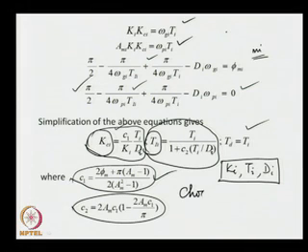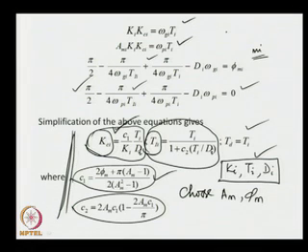So, choose the phase and gain margins for your loops, a m and phi m. Once the phase and gain margins are chosen for the loops, then C1 and C2 constants are obtained. Using C1 and C2 and the knowns Ki, Ti, Di, it is not difficult to estimate the unknowns KCi, Tii. Thus, we estimate the unknown controller parameters using the final expressions given here.